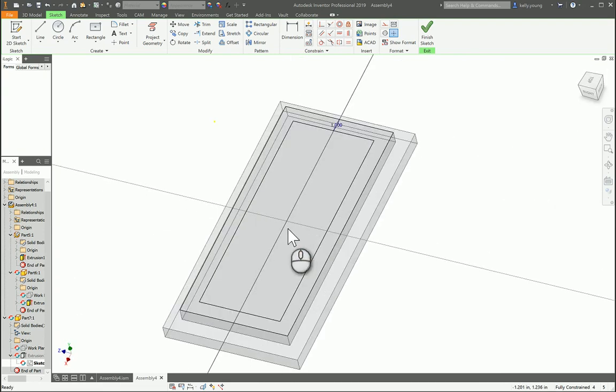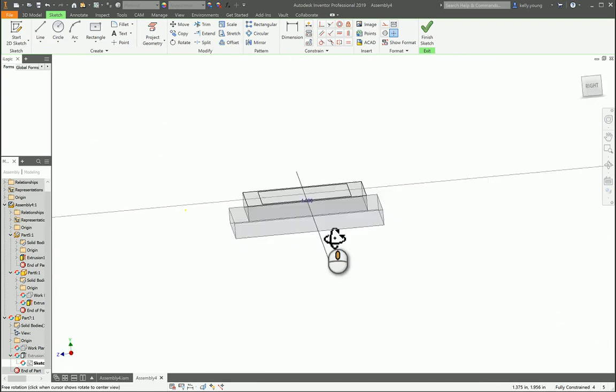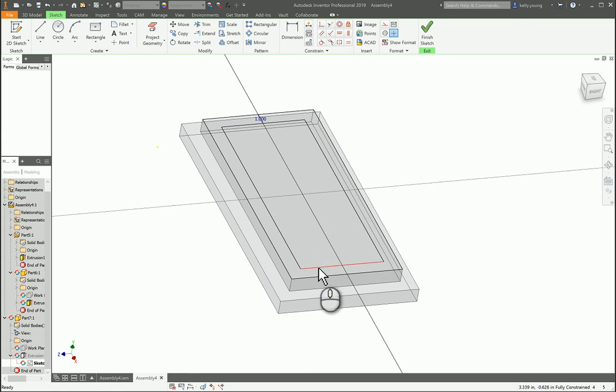So you might have issues with that because basically then it can move all around. There's no dimensions set up because the outside doesn't have that definition. So you'd have to come back in and actually define this. So as you'll see, 6 extensions needed to reference. So it's basically not locked to the origin anymore. So anyway, that's not really what we're talking about.